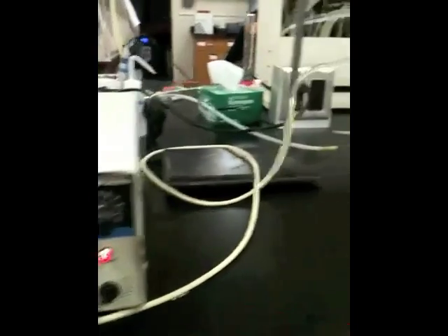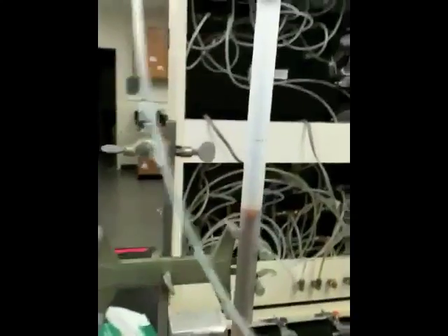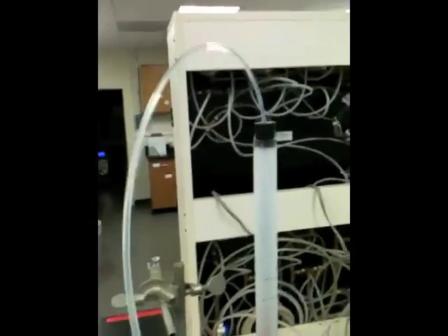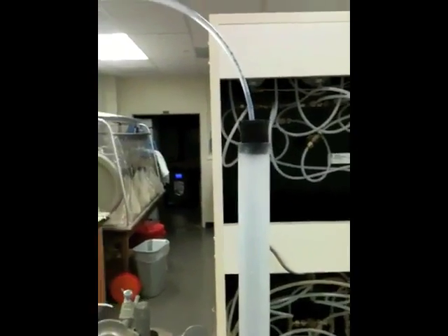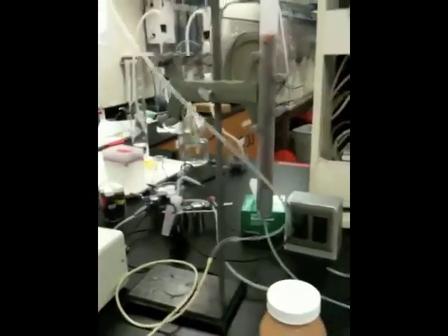Breakthrough curve analysis. The actual capacity of the column bed to remove ions can be determined by conducting a breakthrough curve analysis. Once all the ions present on the surface of the resin substrate are exchanged, the bed is said to be exhausted.